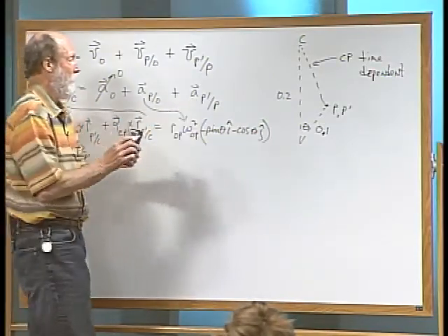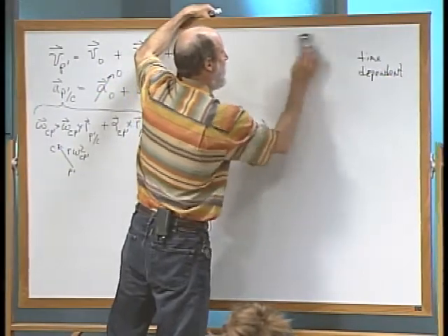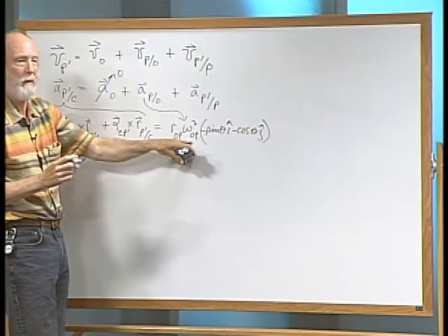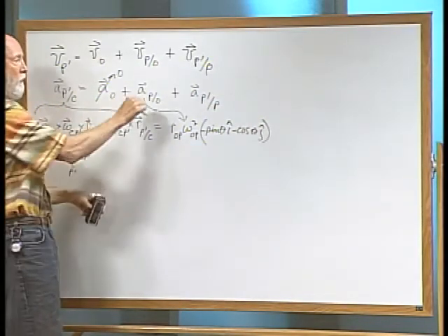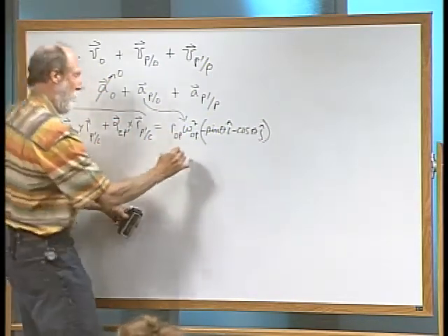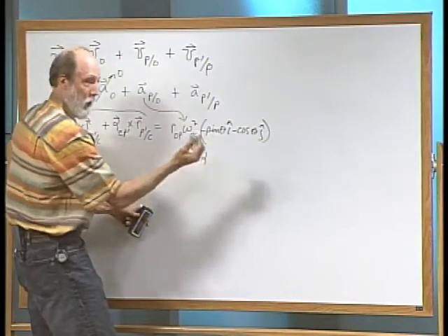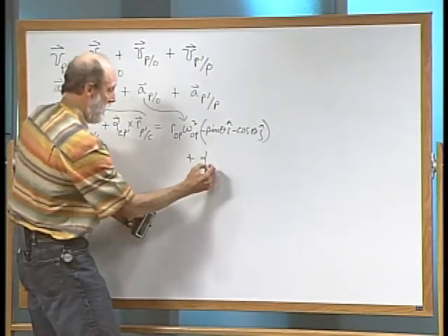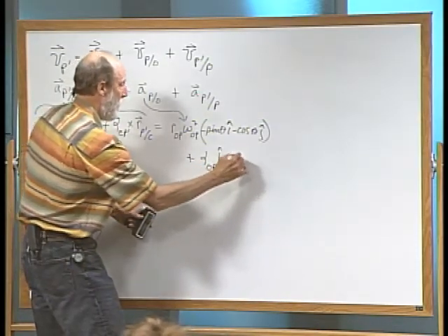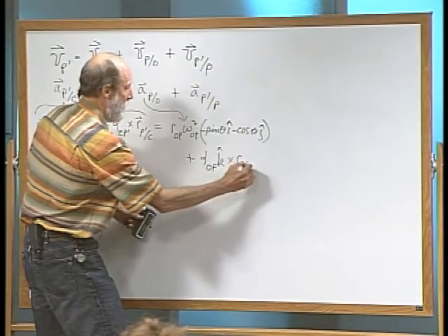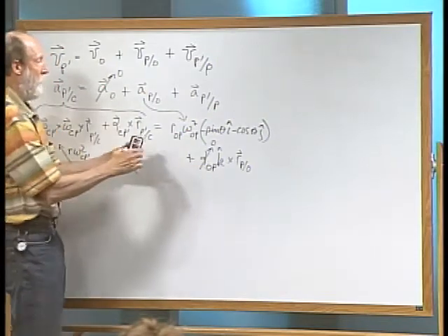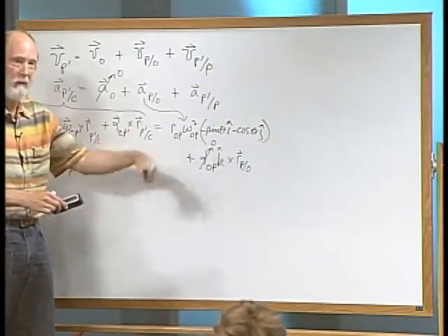And then finally, this last one, oh, and there's no alpha on this guy, on the rotating wheel, right? No alpha. There could be potentially in this problem, if we had other information provided, an alpha of OP k hat crossed with r of P relative to O, but this happens to be zero because the wheel is rotating at a constant speed.